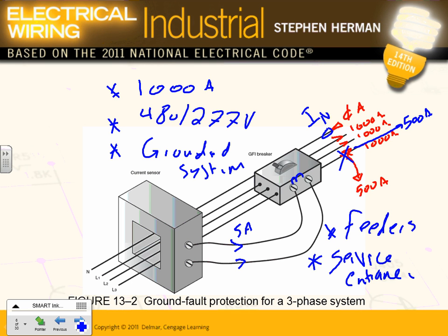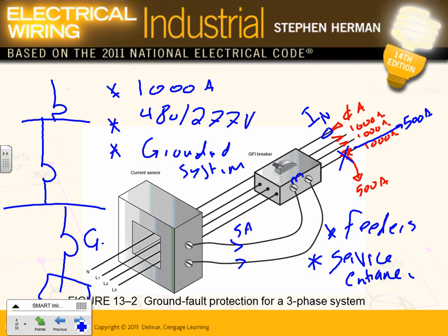In hospitals, they require you to have at least 2 levels. Here, they have 1 level. A lot of engineers can have multiple levels, guys. When they have a ground fault, they have one ground fault protection here, and in a lot of engineering firms, one here and one here, down to the equipment. So this will be ground fault protection number 1, number 2, and number 3, and these will be coordinated. I'll show you in a second how they coordinate. Any comments, any questions, guys, about the ground fault?